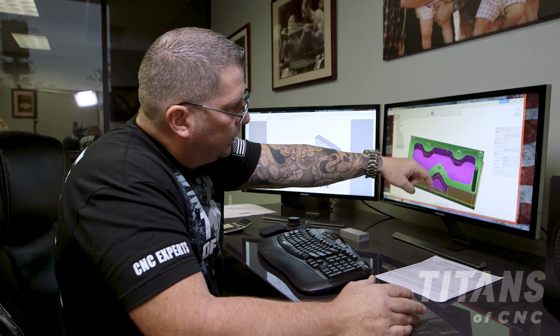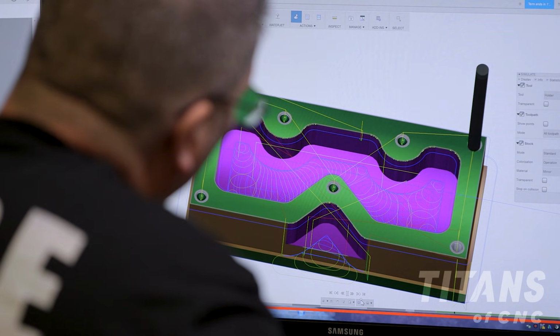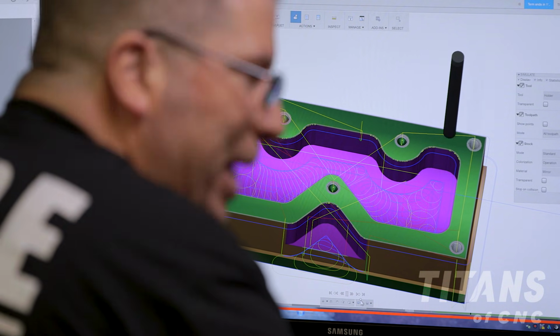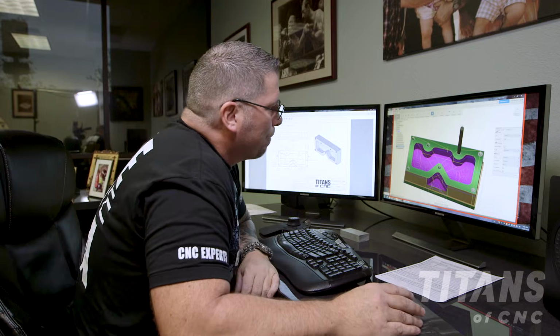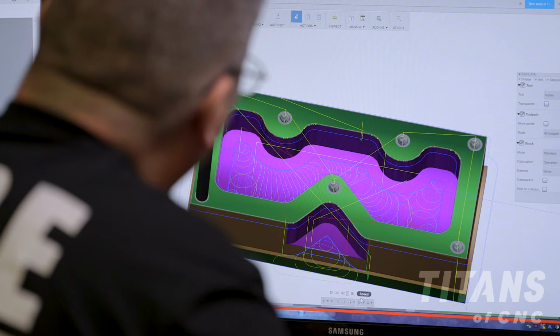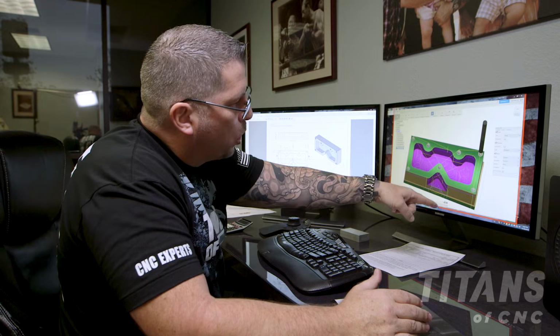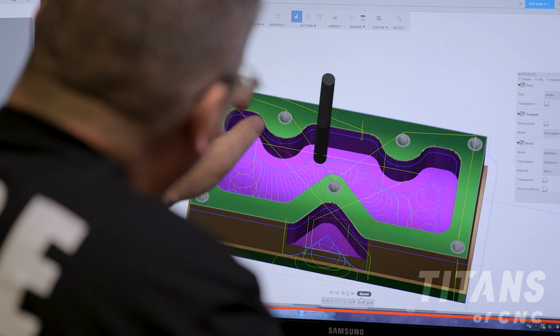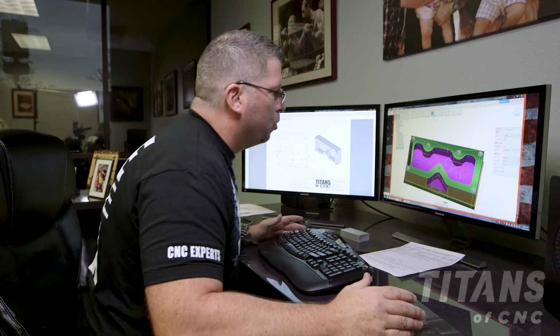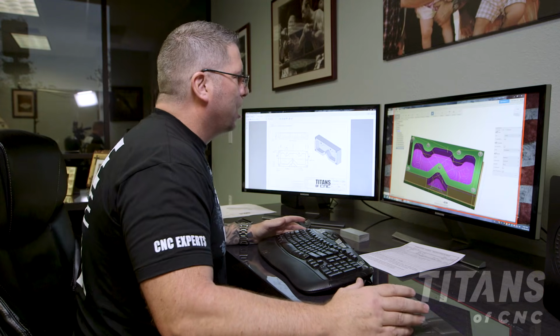Now we're drilling 580 deep, drilling the holes. It's so exciting, it looks perfect. And then we just have our 10-32 roll tap. This is gonna come right after it. Boom, threading, threading, threading. Whoo, mission complete. We got our part.